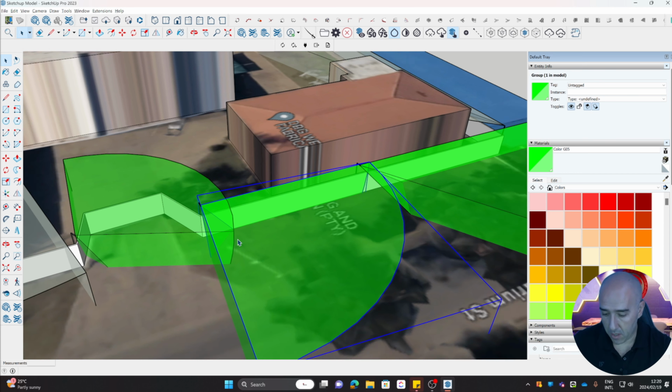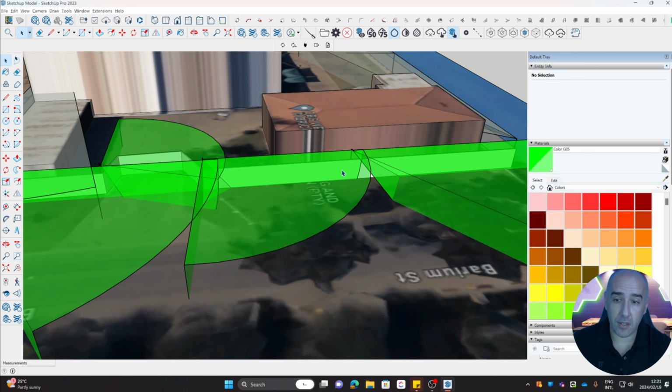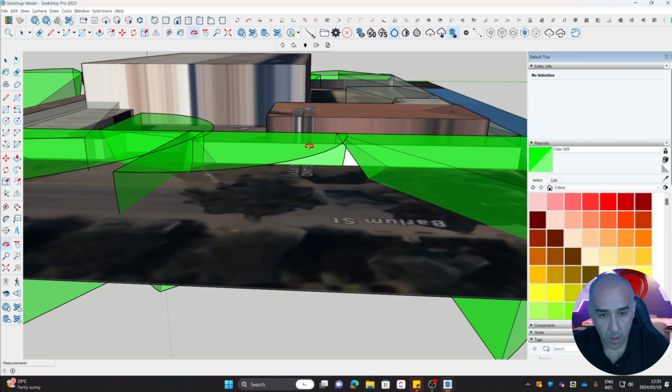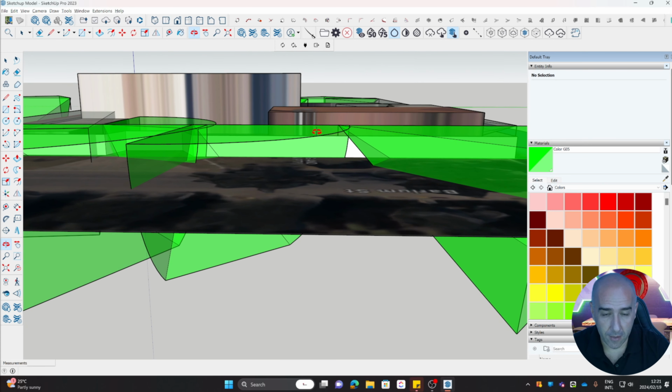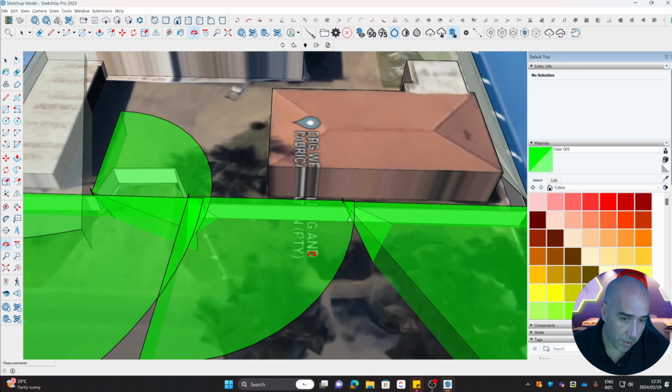So in the front, we are actually using 4 cameras in the front. And again, 3D is now telling me something else. Yes, we fixed this blind spot, but we've created another one with a 4mm. Same situation, very hard for this person not to be detected just by moving slightly. But the risk is there and you have to tell your client about it. If he's comfortable with it, he signs off, you're good to go.